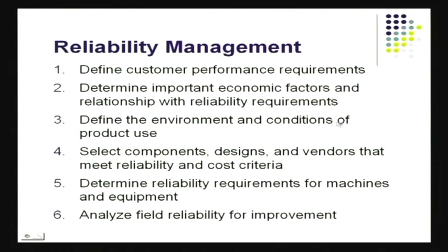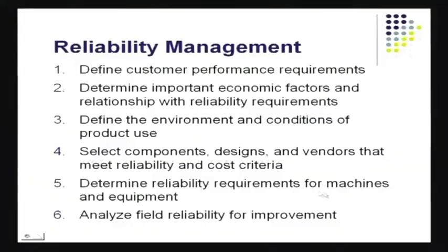Reliability management. How do you end up managing reliability? Start with customer performance. Determine the importance of the economic factor, for example downtime, what it is going to cost you. Define the environment and the condition of products used. Select components, designs, and vendors such that you really meet your reliability criteria and the cost criteria. Both of those you've got to be able to take a look at.